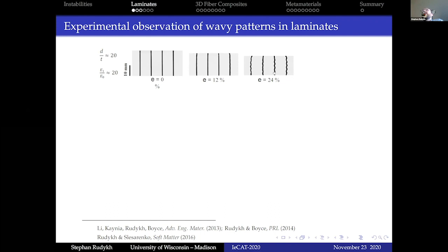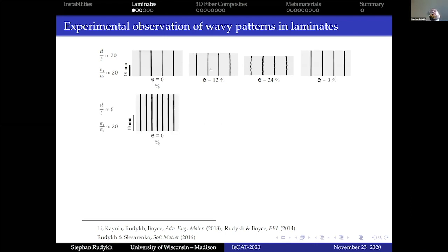And the wavelengths to which they develop will be regulated by the surrounding matrix, because now they need to somehow communicate to each other and decide what they will do together. So just to illustrate the geometrical changes that will happen if we increase the volume fraction of the stiffer phase.